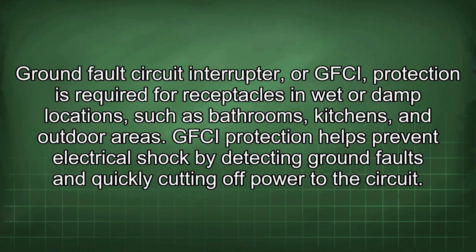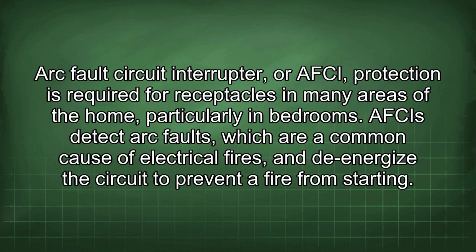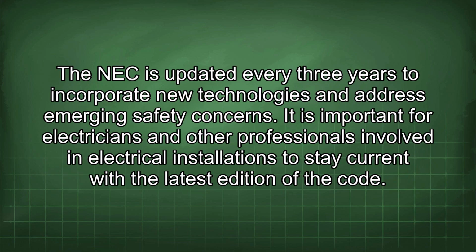Ground fault circuit interrupter, or GFCI, protection is required for receptacles in wet or damp locations such as bathrooms, kitchens, and outdoor areas. GFCI protection helps prevent electrical shock by detecting ground faults and quickly cutting off power to the circuit. Arc fault circuit interrupter, or AFCI, protection is required for receptacles in many areas of the home, particularly in bedrooms. AFCIs detect arc faults, which are a common cause of electrical fires, and de-energize the circuit to prevent a fire from starting. The NEC is updated every 3 years to incorporate new technologies and address emerging safety concerns.